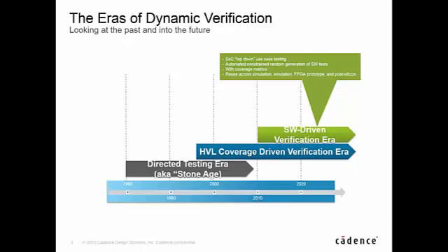And so this is the era that we refer to as the software-driven verification era, looking at SOC top-down use case level testing, and automated constrained random generation of software tests. Obviously, maintaining what we've learned from the value of coverage metrics and applying them at this SOC and system level, and then the ability to reuse all of those tests across the many platforms that have to be utilized during the process, from simulation, emulation, prototyping into post-silicon, as we've been talking about.